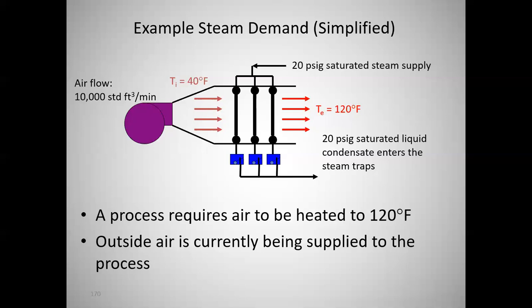Even in the wintertime it'll be 85 or 90 because of all the heat loss from the boiler and the equipment. Where does that hot air go? It rises to the ceiling, sits there until the heat gets transferred to the roof and goes back out to Mother Nature. So one thing we do on boilers is pull combustion air from the warmest place we can get it, because that's less fuel input. Well, this is kind of a variation on that.